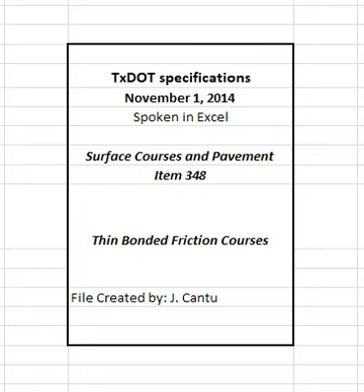Ensure that at least 50% by weight, or volume if required, of the material retained on the number 4 sieve comes from the Class A aggregate source when blending Class A and B aggregates to meet a Class A requirement. Blend by volume if the bulk specific gravities of the Class A and B aggregates differ by more than 0.300. Coarse aggregate from RAP and recycled asphalt shingles, RAS, will be considered as Class B aggregate for blending purposes.